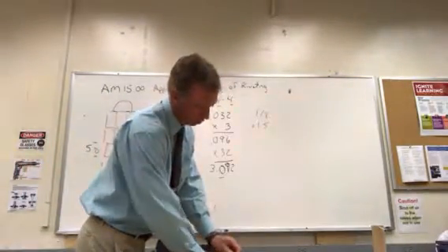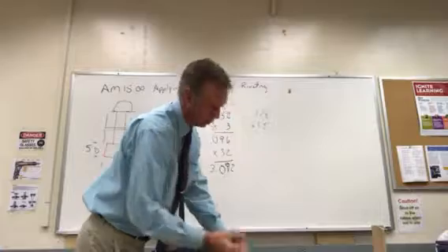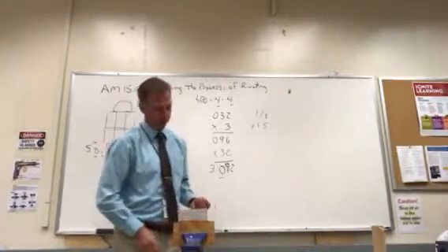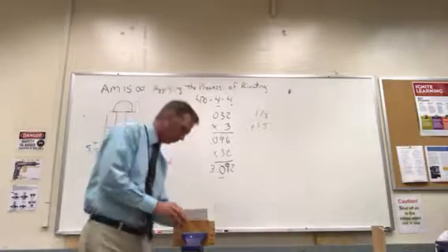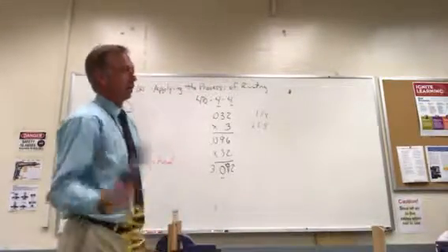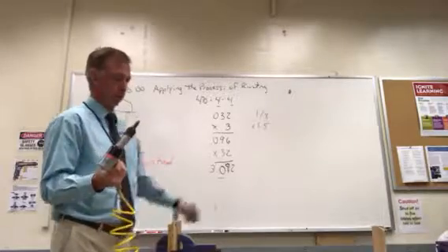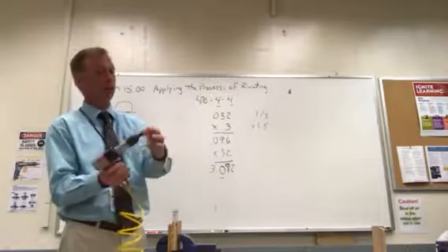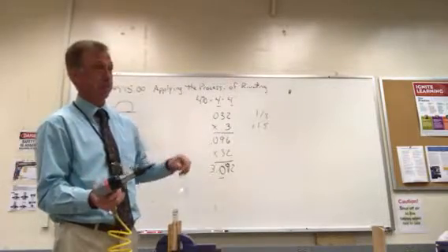Wonderful. So now what we have is I've got a -4 rivet. I'm going to put that -4 rivet in there so it now sticks through. Any rivet set work? No. What rivet set do I need? A -4 rivet set. So I need the -4 rivet set.